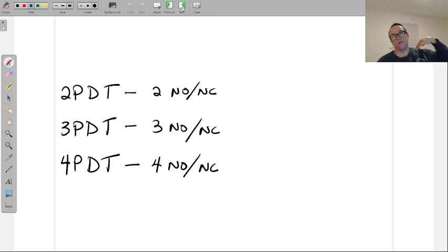If I also want 8 green lights to turn on at the same time for each of the motors, then I'm going to need more normally open contacts. And here's where for lights, yes, you can throw in some auxiliary contacts to help you with a green light, red light turn on the way we've used it in the labs. It's okay. I'm not saying don't use an auxiliary set of contacts. They do have a place.